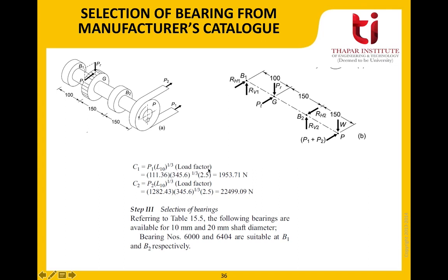So what is this load factor? The forces acting on the bearing are calculated by considering the equilibrium of forces in vertical and horizontal planes. Now these elementary equations do not take into consideration the effect of dynamic load. The forces determined by these equations are therefore multiplied by a load factor to determine the dynamic load carrying capacity of the bearing. So that is what this term represents, to take care of the dynamic forces acting on the bearing.